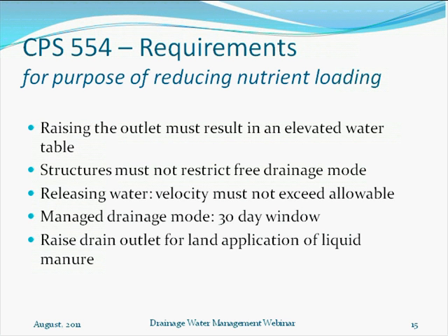That could be a problem. You might even blow out your structure. And so we need to make sure that when water is released, those flashboards are pulled gradually. Typical designs also include a solid pipe near the structure so that the piping near the structure is more resistant to high velocity flow.